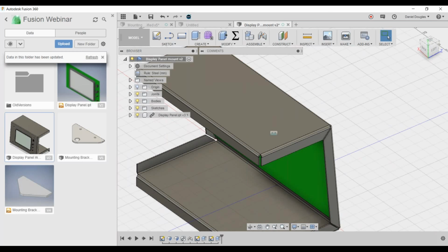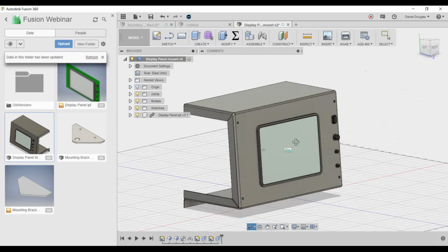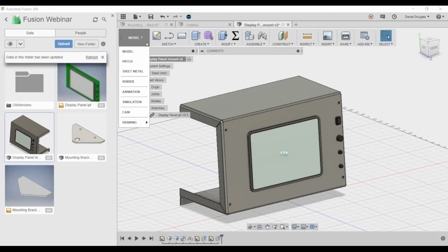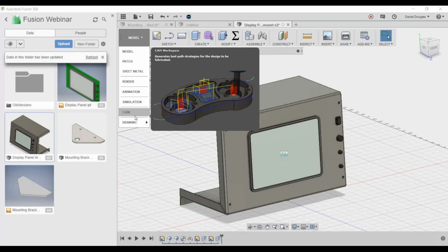Whatever you're doing, for example if you're running CAM toolpaths, those are adaptive to changes in the model. When you reference in a model, instead of recreating or doing a dumb link, not a live link, a change in the model might require you to redo things, because when you import a new model, the face IDs are not going to be the same between previous and new. So for workflows like CAM, where you're picking a face and letting the toolpath calculate, if the face updates, it's automatic. You don't have any extra work to do.